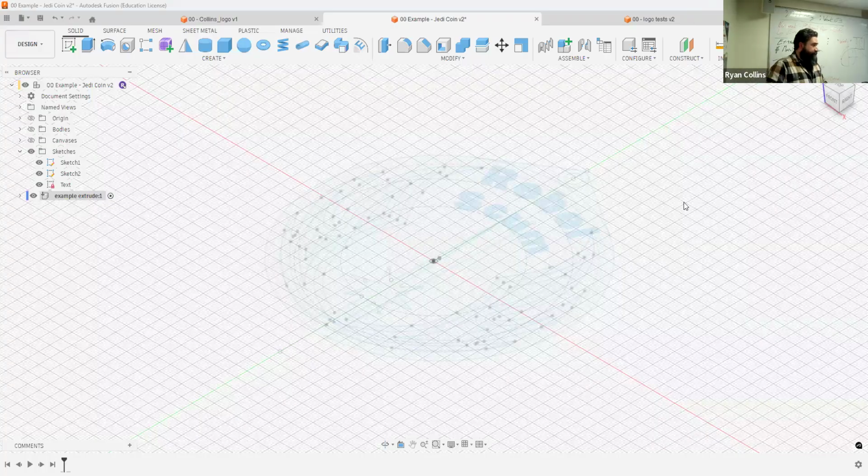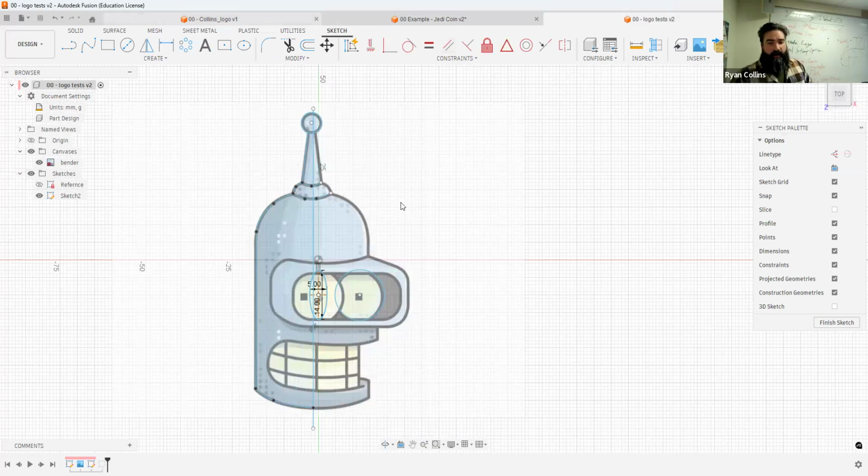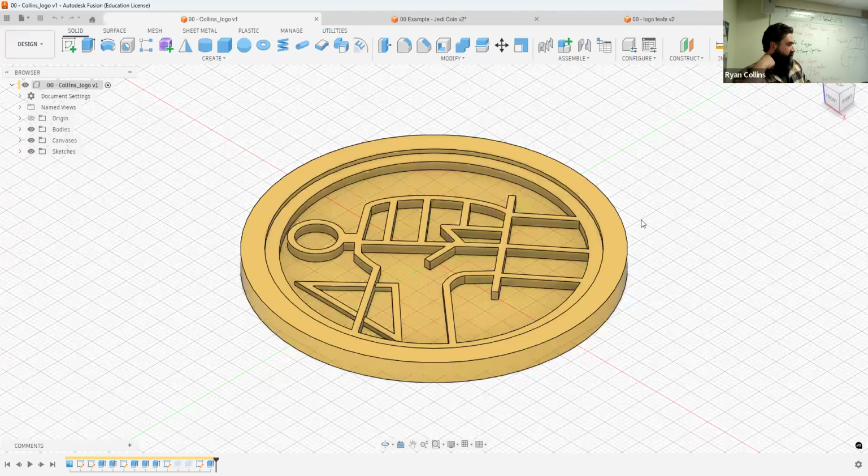Okay, so just for the sake of time, I jumped across from my Blender thing because I need to finish up here so we have enough time. I want to show you how to create your logo to actually create the extrusions. One of the main things is that you can't just have floating parts. You need a background or something to attach to. If you've got text, that works great, but you do need a background, because otherwise you're going to have disconnected singular objects. The same goes if you use the extrude to cut through and make a recess: you need a background, something to that effect.